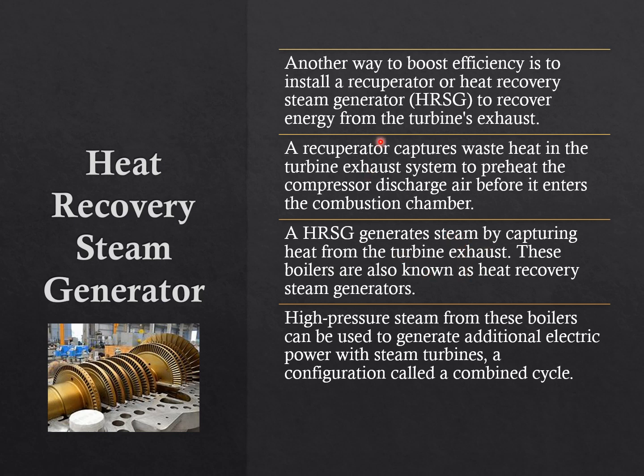Here you reheat the compressor air. Here you produce the steam by using that waste heat. And we call these boilers heat recovery steam generators, which is your HRSG. So in short, you can think of the recuperator as using the waste heat to preheat the system. The other one, the heat recovery steam generator, uses the waste heat to produce steam.